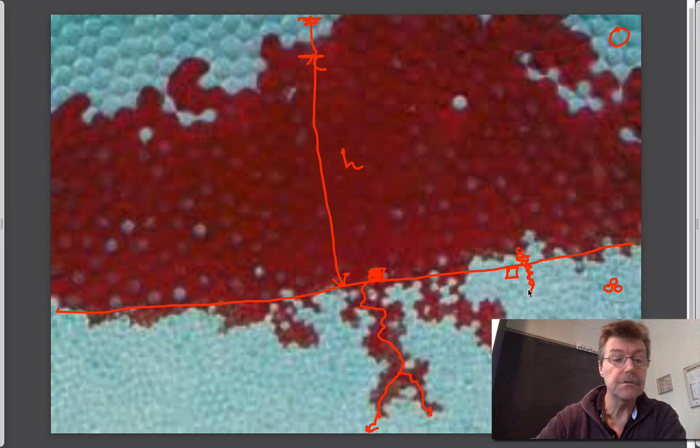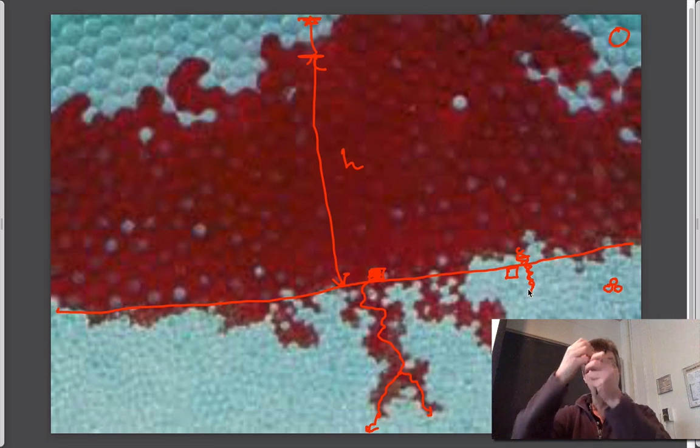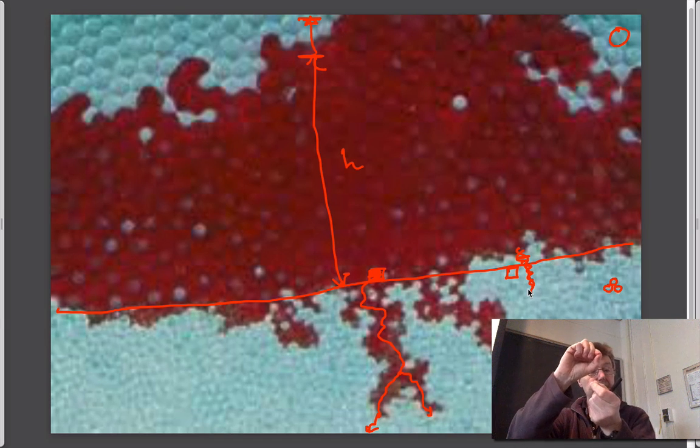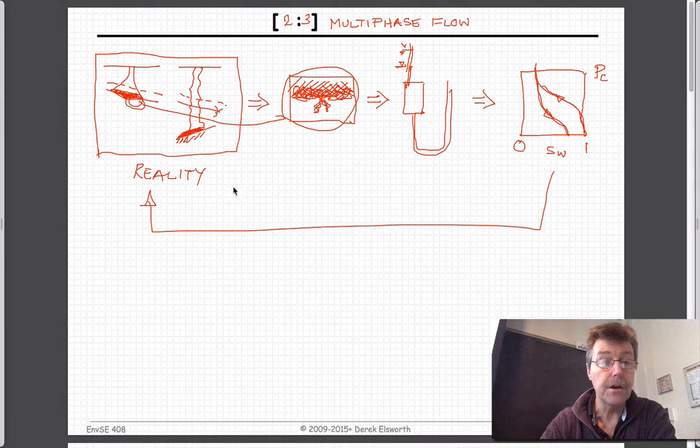And we understand it in terms of capillary behavior. The basic idea is that the only driving force in this is the weight of the water, which is pushing down, and it's resisted by the interfacial tension, which is actually a very big force per unit volume, pushing back. If the pore throats are very large, there's a very heavy tube and very little capillary resistance, and so it keeps on going. If it's very small, still the head gives the same pressure there, driven by the same weight of water, but the resisting force is relatively large in that case, and it resists it and stops it going over. So that's the second part of our understanding in terms of this.